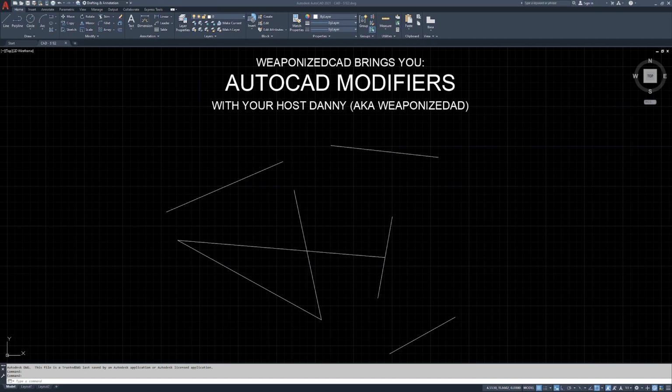This is Danny. Today we are talking about AutoCAD modifiers. In the last episode I said that we were going to move from the line command to the polyline command, but it actually makes more sense now that we have some lines drawn to move into the modifiers and then bounce back to the polylines, because we have objects we can manipulate now with these lines, and we're going to start running through some of the modify commands.